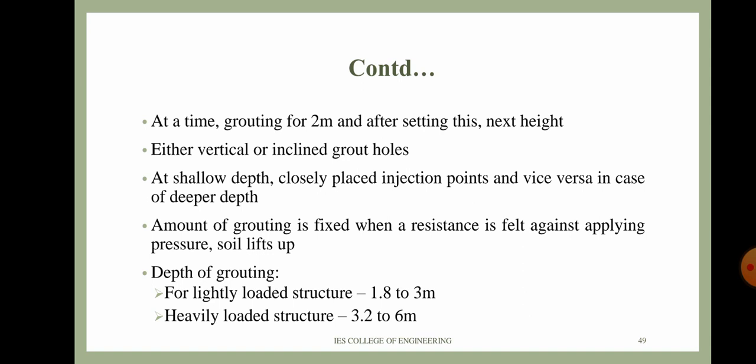this resistance results in the lifting up of the soil and forms a heap formation. The depth of grouting in the case of compaction grouting, for lightly loaded structures, varies from 1.8 to 3 meters, and for heavily loaded structures, this grouting depth varies from 3.2 to 6 meters.